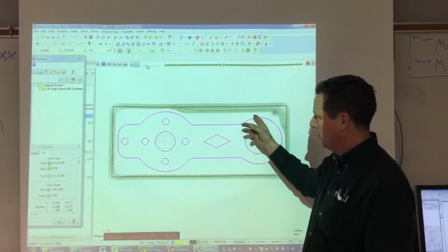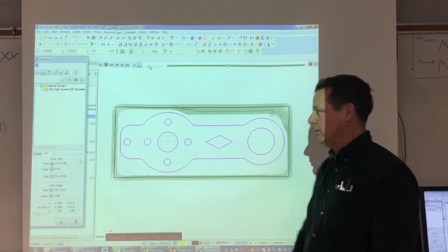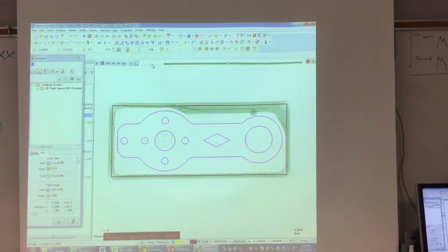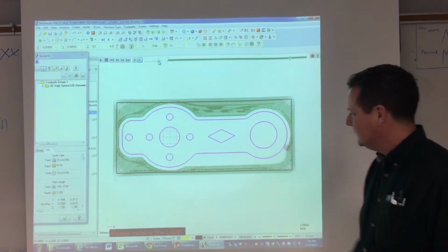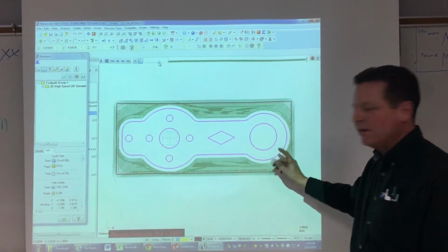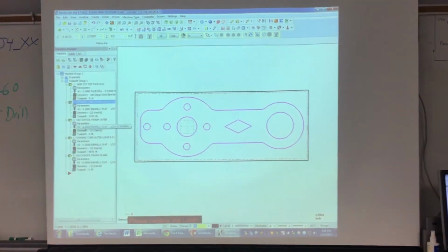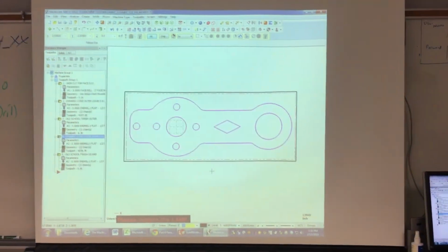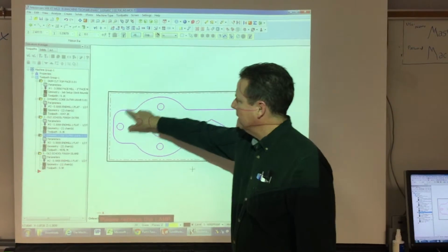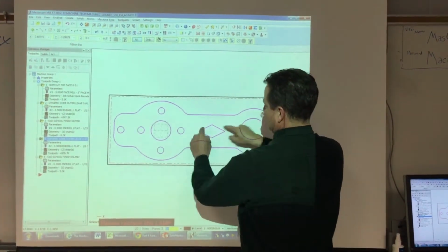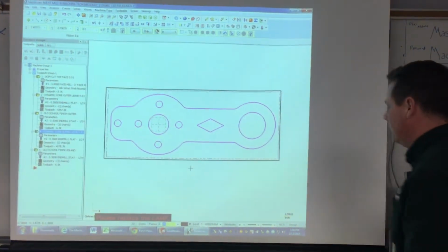However you approach the part correctly, it gets rid of the metal 70% faster than the old ways we used to do it. So I'll zoom this up faster, and we'll watch it cut all that stock away, picking its lines, and trying to stay in contact with the metal as much as possible. So we did that for this one, and it went around the outside of the part, and then since we had only this left, we did another core outer to leave this island standing up.